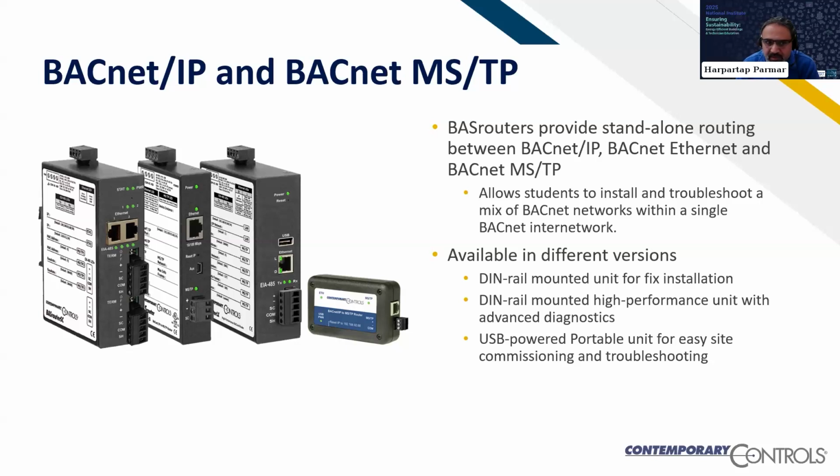There are different versions available for BACnet routers. We have DIN rail mounted versions for fixed installations. The other version is a USB powered portable unit. For people who are just doing site installs and commissioning, you can power it using your laptop, and a simple web browser can be used to look at the settings.